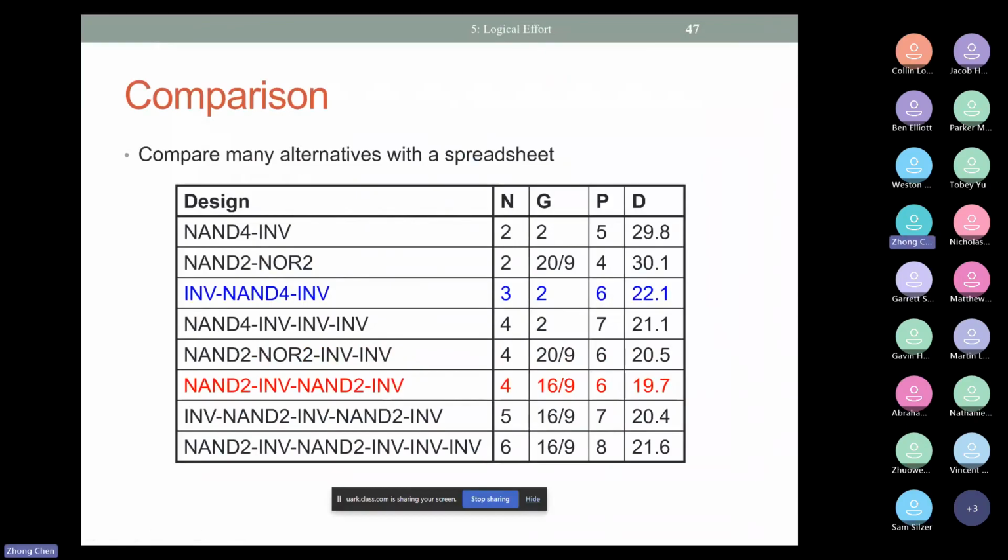Okay, so here, the middle one is what we have tried, with the inverter, then 4-gate inverter. This is one of the designs. You can also try a different, like a 4-stage design, then 4-gate inverter. That is another kind of design because you can change your inputs. Not use an inverter to drive. You can use a NAND 4 gates to drive, but input capacitance you can still keep at 4. So then the rest of them you can use inverter, adding the inverter.